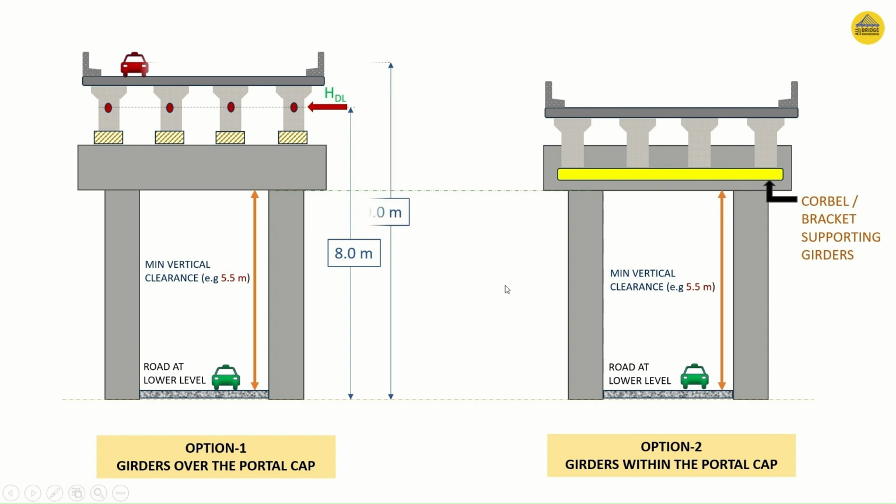this, horizontal forces also act on live load or vehicles that move over the carriageway. Some typical examples of horizontal forces that act on live load are: in the transverse direction, wind force acts on live load, and if the alignment is curved in nature, then a significant amount of centrifugal force also acts in the transverse direction. They are also part of horizontal forces acting on live load. In the longitudinal direction, we do have braking forces acting on vehicles. They also contribute to huge moments in the longitudinal direction.